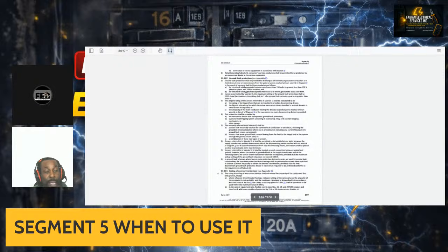You're going to find that rule, the 80% rule. It is in there. Basically, what the 80% rule is, you cannot max your circuit out. You have to have enough left over for the circuit to work accordingly. Again, your breaker protects the wire, it doesn't protect the device. A lot of us get confused and somehow think the breaker is there to protect the device, but it's not protecting the device, it's protecting the actual wires themselves.